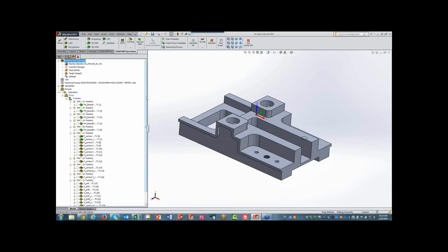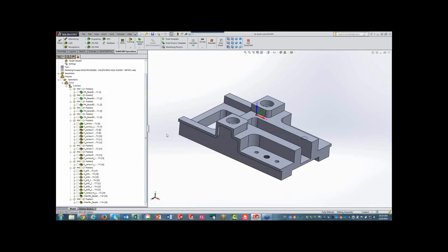Now, if we take a look at all my operations over here, I had to do a total of 26 different operations to work over here. Okay? To do all of this, 26 different operations. He's showing you now if you are doing 2.5D milling. Right, this is regular 2.5D milling. Now, I'm not going to show it to you right now in iMachining 2D because you saw already the advantages of the cutting time in iMachining 2D. The amount of operations, I still may have to have the exact same amount of operations. But let's actually start doing it now with iMachining 3D.